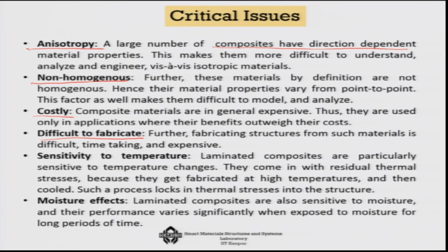Then there are difficulties to fabricate. I told you that some of them at a very small scale are very difficult to fabricate. They have sensitivity to temperature very much. The usual polymers themselves degrade because there are polymers there. So, the polymeric composite itself degrades. Further to that, some of the smart materials will suffer from the Curie temperature. So, it has the sensitivity, and then of course, the moisture effect, because laminated composites are in general sensitive. So, you have to consider that while modeling such systems.